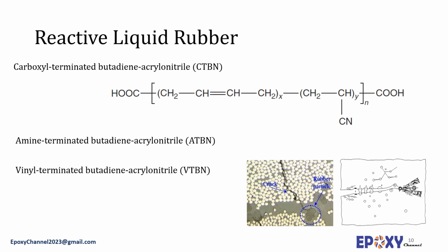Early structural epoxy adhesives were based on epoxy resins modified by liquid butadiene acrylonitrile polymers with terminal carboxylic groups. By using low levels of these liquid polymers, the fracture energy of the cured diglycidyl ether bisphenol A type epoxy resins increased by a factor of 15. After the cure is complete, the adhesive consists of an epoxy matrix with embedded rubber particles.